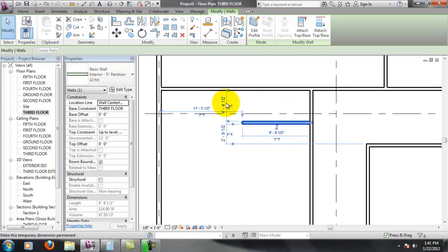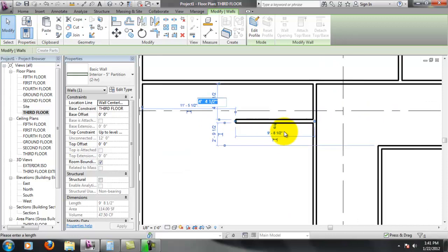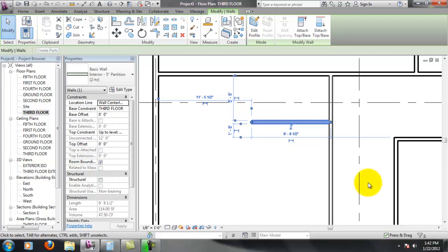I'm going to make sure that I have my space that I need here. I'm going to need at least 5 feet because for a wheelchair turnaround circle, in order for a wheelchair to turn around, you need to leave a diameter of 5 feet or 60 inches. So I need at least 5 feet here. And this, like I said, is a huge, huge floor. There's no reason to be stingy here. So I'm going to go ahead and make this 5'6" for a comfortable turnaround. All right.